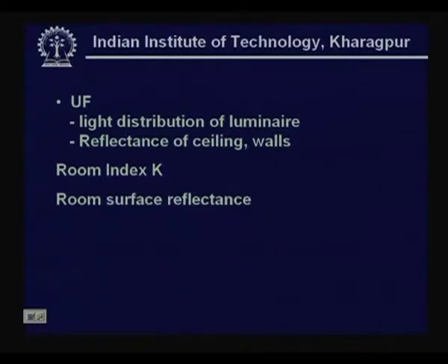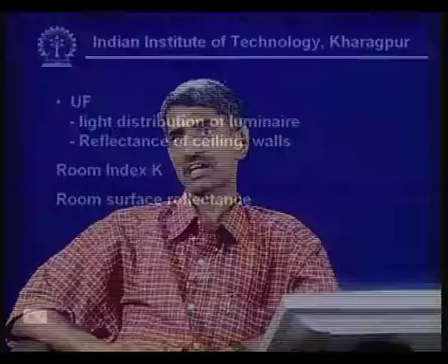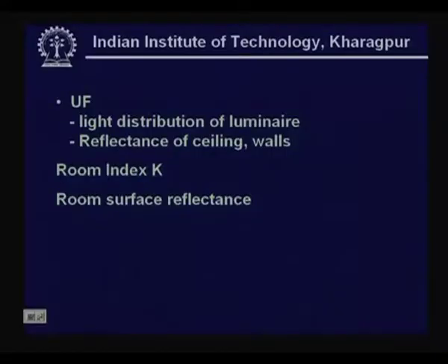Keeping this in mind, and keeping the reflectances, remember there is some light on the wall area above the plane through the luminaire, which we call frieze, that goes waste, and depending on the dimensions, the CIE recommendations talk in terms of what we call an index.